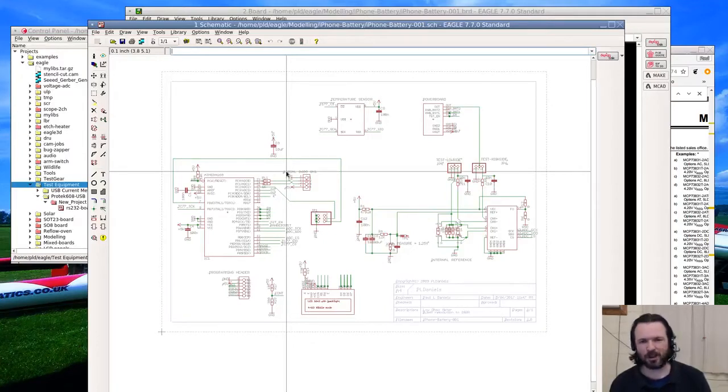And what else do I want? I was going to have it a blind device, with nothing other than maybe a blinking LED. But I think I'm going to put a 16x2 matrix display on there. They're cheap and easy to drive, and it can be useful to just look at the status, particularly if you're not looking at the computer right then. It also gives it the ability to be a standalone unit. The last thing we have to think about is interfacing the charge and discharge to the battery itself. I don't want all the different connectors dedicated on this board, so I'll probably do a daughter board.